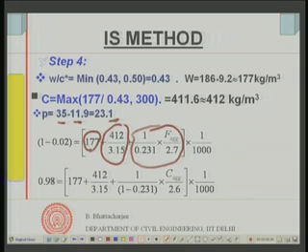This sum total of the volume, all divided by 1000, must give me the volume occupied by everything other than air in 1 meter cube, and this is the volume occupied by air. 1 is the total volume minus this. So, this is the volume occupied by all this material. This is the equation I use to find out the value of fine aggregate.